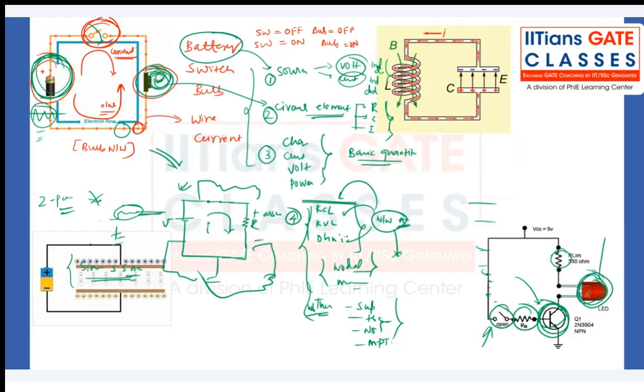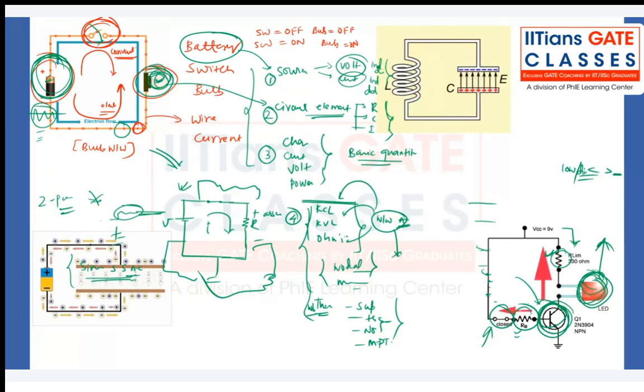As a network engineer, see, if this particular LED is having a light, let's not confuse with the unit, right? Let's assume that it is low or dim, right? I wanted to increase the light or illumination of this one. What I can do, I will pass more current. How I can pass more current? I have to play with the resistors only, right? Because this transistor is working as a switch, I have to play with the resistors, right? To play with the resistor, you should be knowing the characteristics of a resistor. How many times I have to repeat, I will repeat. But as a network engineer, you should be knowing the characteristics of a particular circuit element, right?